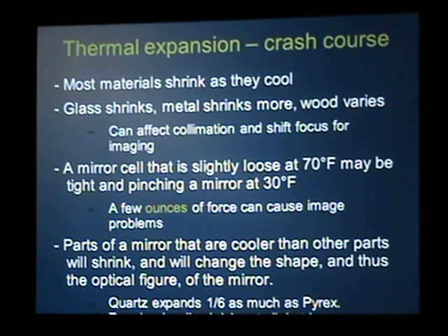The advantage of quartz is that it expands or contracts 1/6 as much as Pyrex. And so this overcorrection effect and other cooling effects from blowing fans on it, which I'll talk about later, are reduced by a factor of 6. But of course, it's a more expensive material.